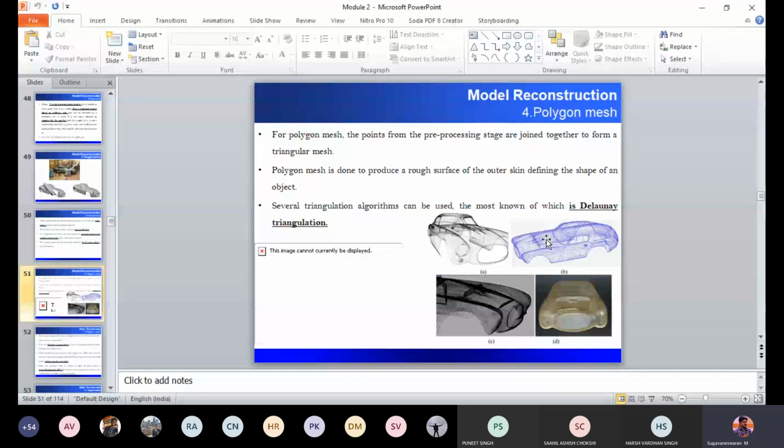If you want to create a cube directly, you are not able to. First you have to create 4 points, then connect those 4 points using lines. If you connect the 4 points, it will become a square. Then extrude the square, and you get a cube. So it starts with a point, then you connect points to get a wireframe model, that is your square. Then you connect the edges of squares to get a surface. Then you extrude a surface to get a solid model.